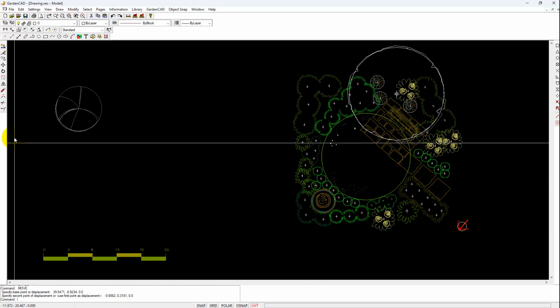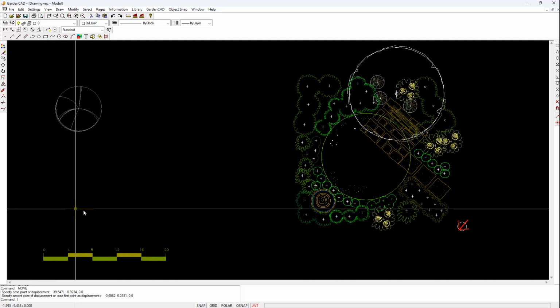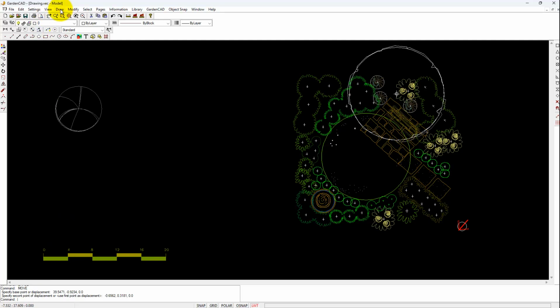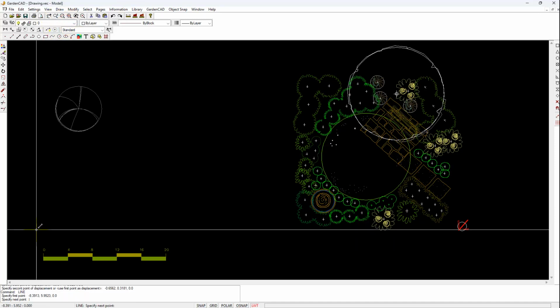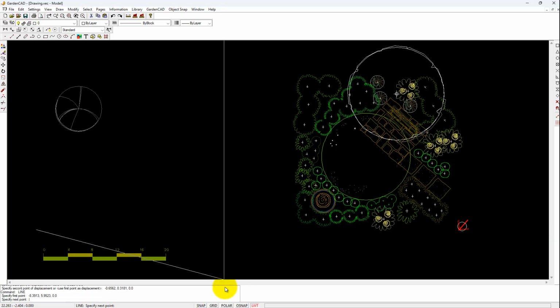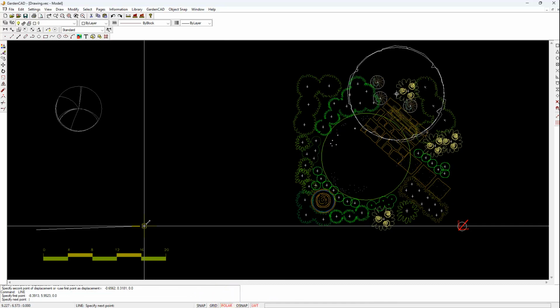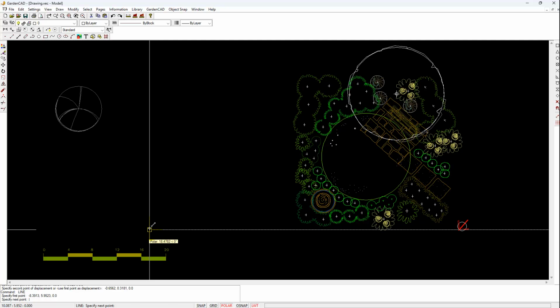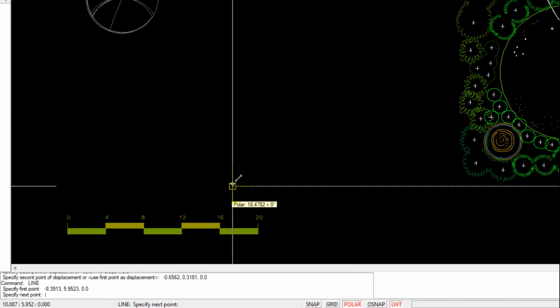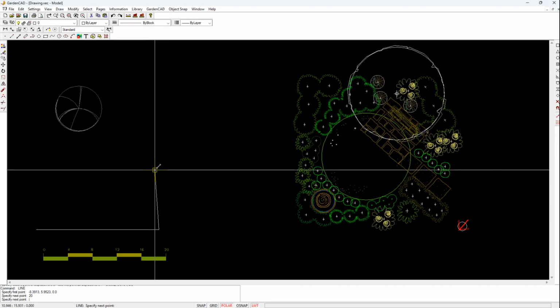So we're developing a drawing, maybe it's a site that you are familiar with. You start by drawing some lines. So draw a line, indicate a start point just by clicking, and then if you put polar on, that will enable you to draw a horizontal line easily. See how the horizontal line locks in? So it's about to draw a line 18.47 decimal feet, work in decimal feet. So let's make it 20 feet, and we hit enter. The line then radiates out.